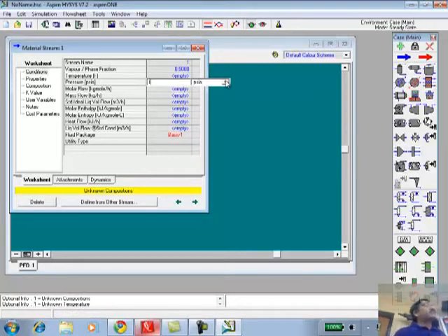Now, it didn't ask me for vapor fraction because it's a dimensionless number. But pressure is a dimensional number, and you can select the units to be anything you want. Okay, so I'm going to say it is 1 atmosphere, for example. Then it automatically converts to 14.7 psia because it displays in that unit. But you can customize these too. Display units can be customized through preferences.